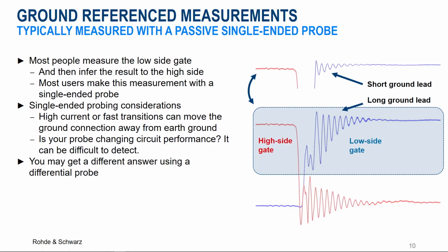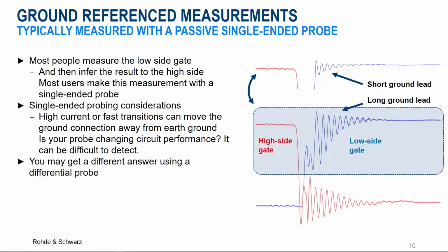As mentioned previously, the long ground lead induces noise and ringing at a lower frequency. Swapping out the long ground with the short ground spring reduces the error-induced noise and will minimize the ringing. An alternative solution is to use a high-performance, high-voltage differential probe to minimize these effects because it has good shielding, low inductance, and high common mode rejection.